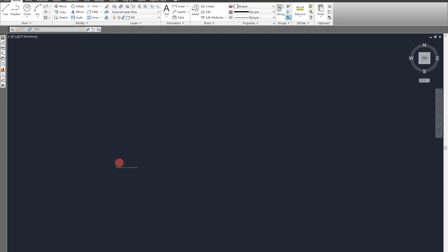The command is designed this way so that when you start drafting, now you will ask first why it is attached to the horizontal line. It is because I've marked this polar tracking. If I unmark it, you can see now it's not checked. It will not be constrained to the horizontal, but it is very useful later on.